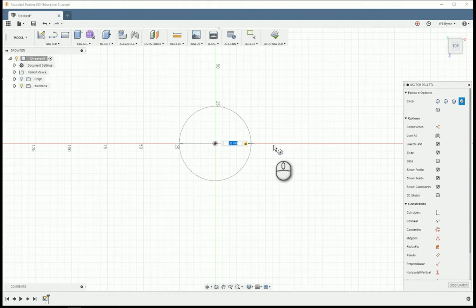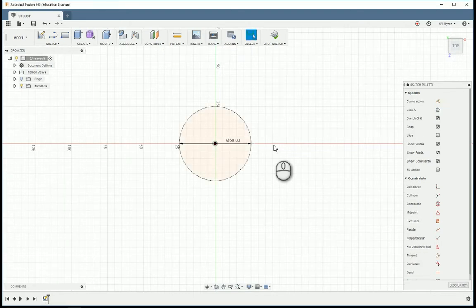A driven dimension is what carries through the design file history forever. So if you try and make a change, it's going to warn you, this is set to be 50, you can't automatically scale it. Are you sure you want to make the change? That way down the line, if you misclick, you're not going to affect every single part before it. It's just the one individual component you're working on. Hit enter again, there you go, and whenever something is properly dimensioned, it'll show up as a number with two arrows going to the quote-unquote datums. You can click on that and rotate it, drag it, pull it to get it out of your view, or if you really don't care, you hit delete.